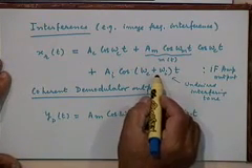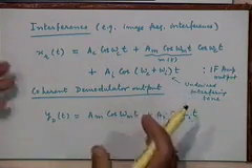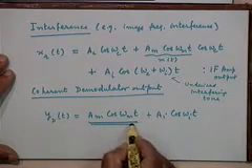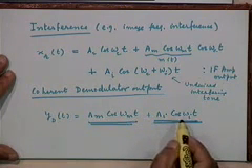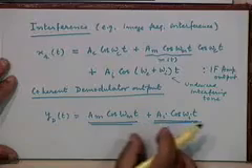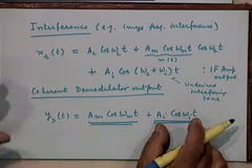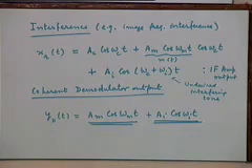So even in the coherent demodulator, you will get an output corresponding to this interfering frequency present in the input signal, right? So even the coherent detector would not work perfectly in that sense. Not only do you get your desired signal, but you get your tone, the interfering tone of frequency omega_I. Is that clear? However, the amount of this interference that you will see at the output will be directly proportional to the amount of interference present at the input, which is something that we accept as communication engineers, right?